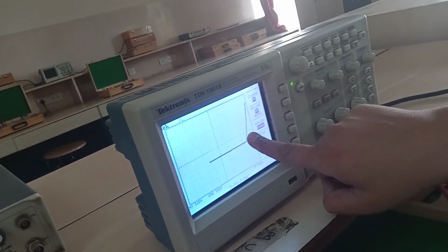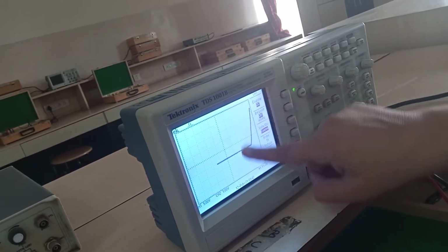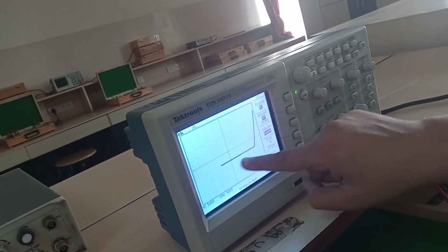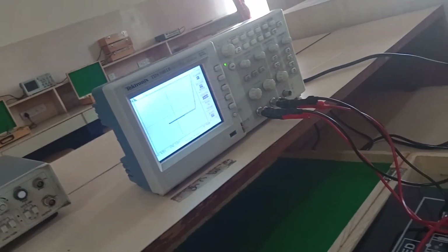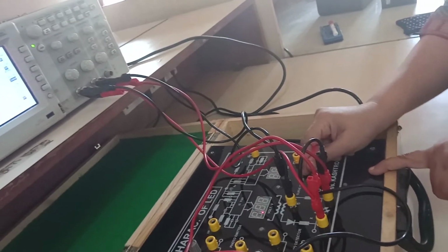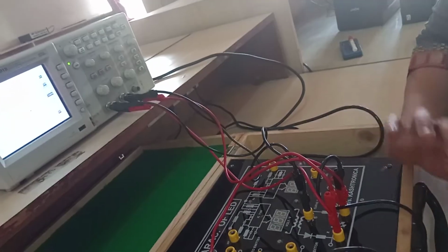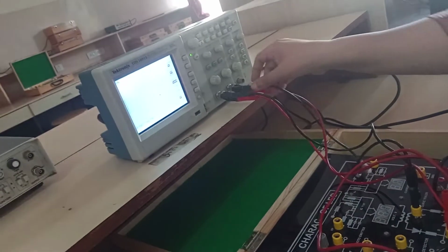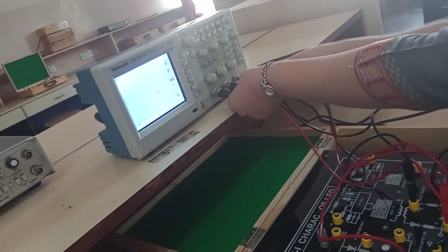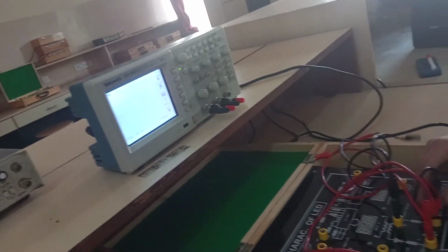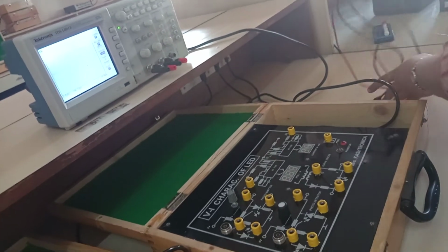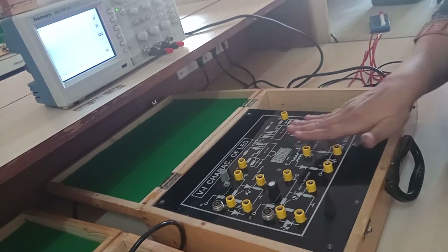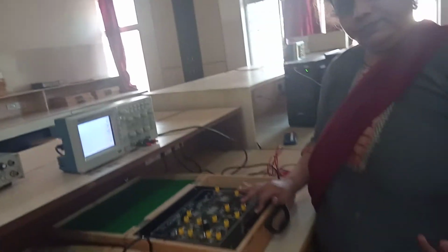This is a PIN diode and previously it was a silicon diode. So that's why this VI characteristics will come at this point. So the cutoff for your LED and photo detector will be different. Afterwards, conclude that all your components are working. Then you don't need any DSO for your experiment. After checking, you can remove the connection. You can even remove the connections from the board also. The curve tracing part is finished at this point.